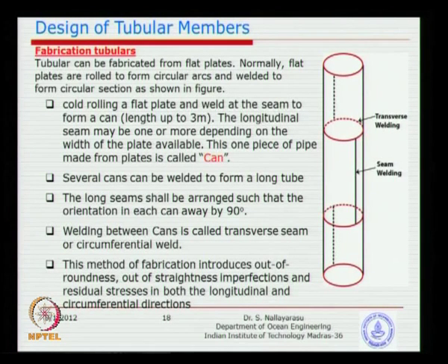You take a piece of pipe, for example, you heat the whole pipe throughout and both ends are restrained. What will happen? Basically the pipe will induce axial stress on the support where it is not allowed to expand. Exactly the same here: a circular section where one section is heated and the other sections are not heated. In the axial and the circumferential directions you may induce additional stresses.